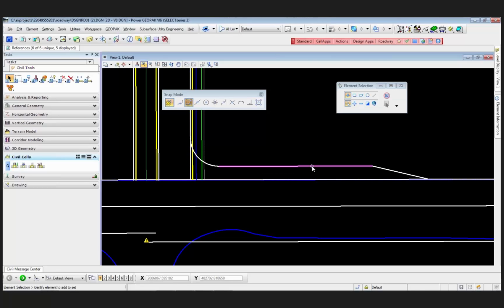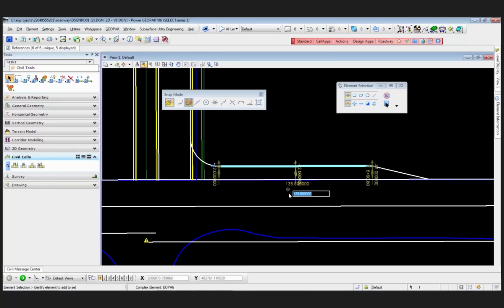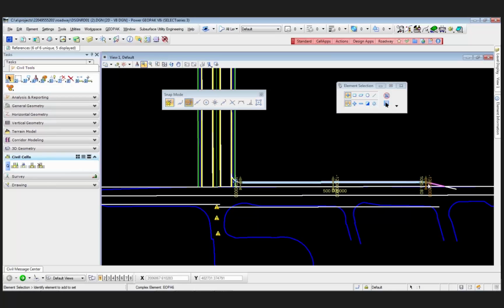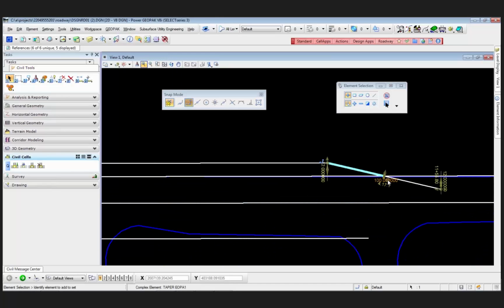And now I've essentially placed the geometrics for the right turn lane out there. And of course, there are some other things that need to be put in here, but for the time being, this is what we've got. And if you want to change this length to, let's say, 500 feet, it's going to change the storage length all the way back there. And if you want to change this offset or change the taper rate, this taper rate is actually set for two 12-foot lanes, but if you wanted to change this to 50 feet,